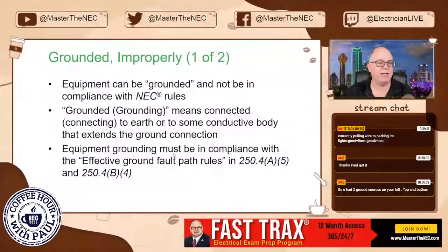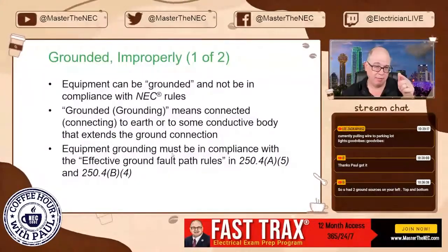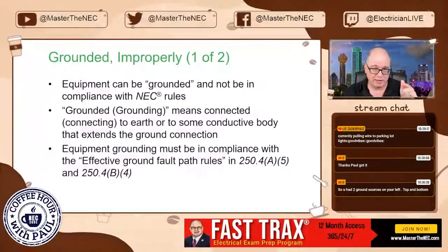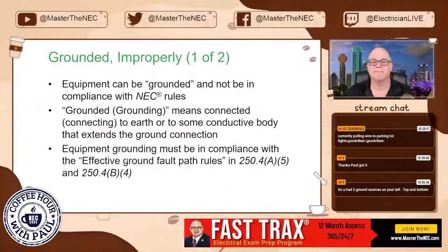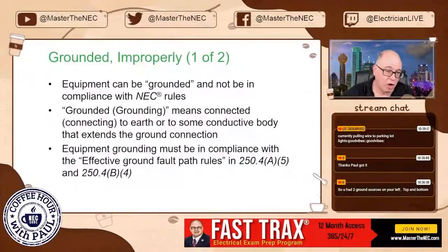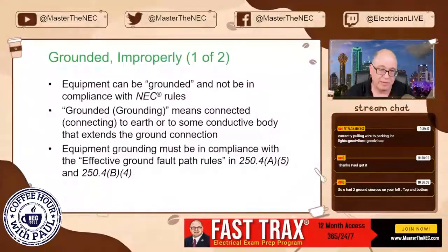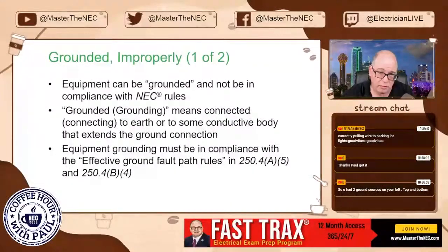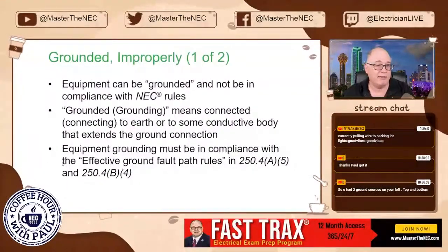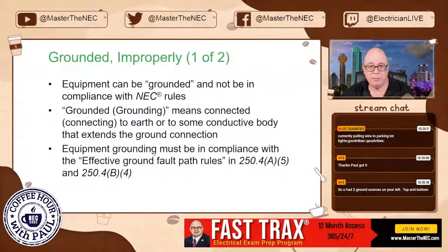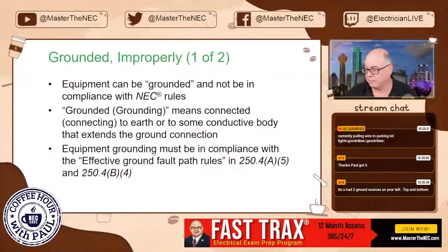Lee's doing some parking lot lighting. Remember, Lee, make sure they always run an equipment grounding conductor out there, okay? Now, I hate to say this, it doesn't always have to be of the wire type, okay? It could be the type of wiring method you're using in 250.118, but I'm a wire guy, so most people want to put that wire in there. They just feel good about it. Put it in there.